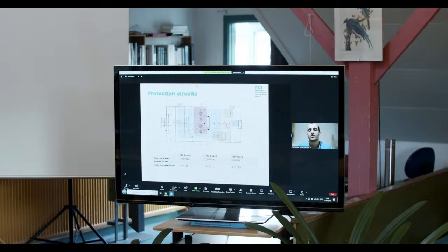To obtain the previously mentioned functionality, here in the top part of the slide we have the electronic circuit design. It can be seen as an addition of different sub-electronic circuits: in blue, the comparator window; in red, the Schmitt triggers; in yellow, the relay governance; fourth, in green, the relay; and finally, the fifth, in purple, the bus capacitance. If you have any doubts about the circuit, you can ask me when the presentation finishes, because we are not going to explain now how all the circuit works.